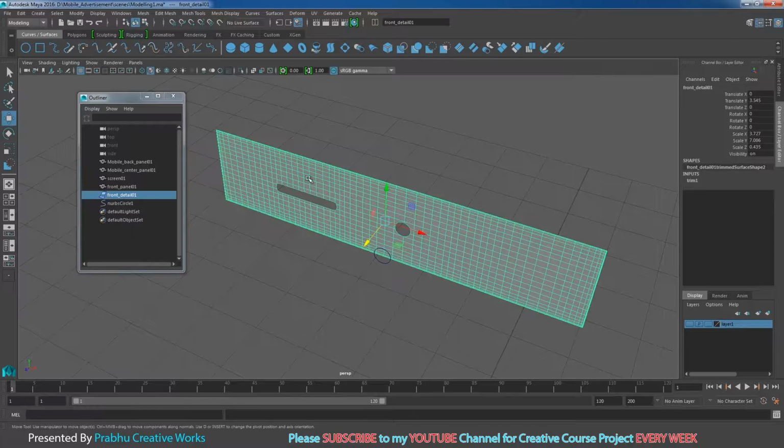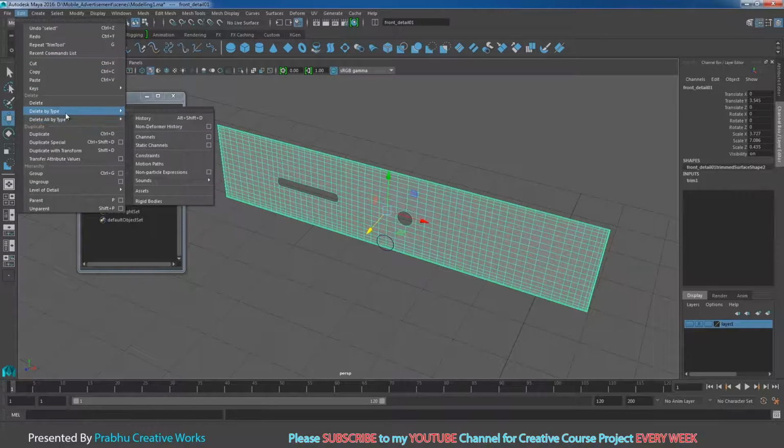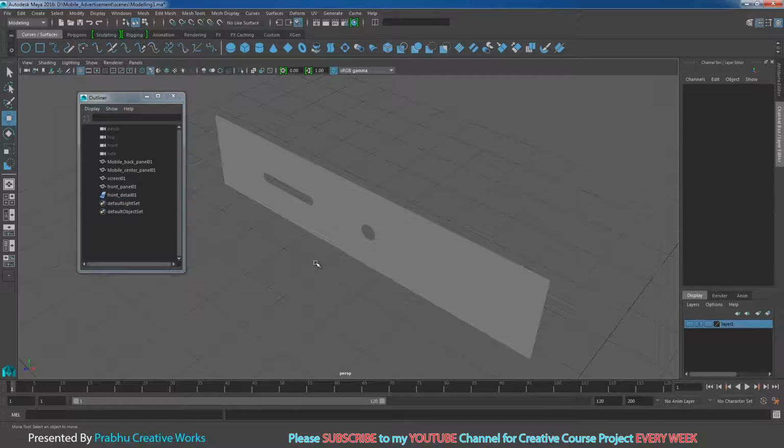So I will select front detail and go to edit, delete by type and choose history. So now I select my node circle 1 and press delete on the keyboard.